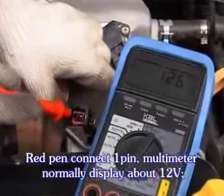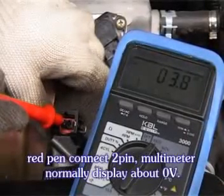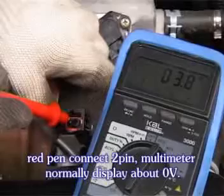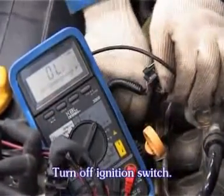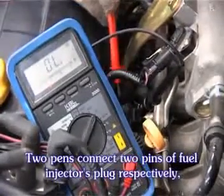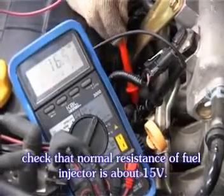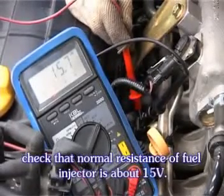The multimeter normally displays about 12 volts. Connect the red pin to pin 2. The multimeter normally displays about 0 volts. Turn off the ignition switch. Connect the 2 pins to the 2 pins of the fuel injector's plug respectively. Check that the normal resistance of the fuel injector is about 15 ohms.